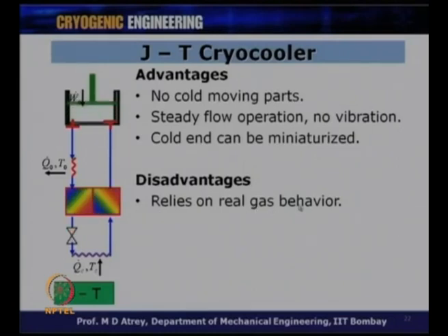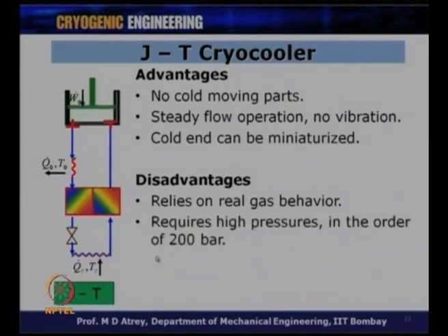So, real gas behavior, we can't use the ideal gas. We have to worry about its inversion temperature. It requires high pressure of the order of 200 bar if I use a single gas, and therefore, the pressure requirements are very high in this case.